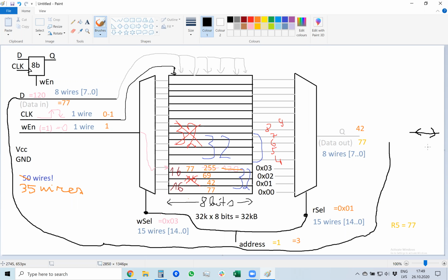However, let's say data in a certain location is 0, and the microcontroller wants to write 1 into that location. If this cable is set high to 1, but this data output sets the same cable to 0, you will have a short circuit,